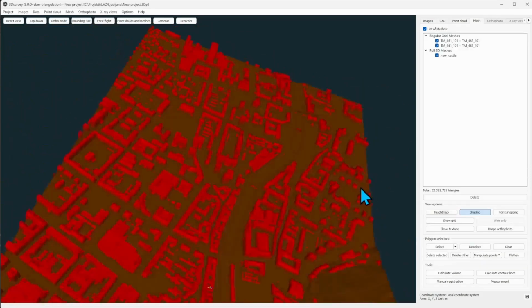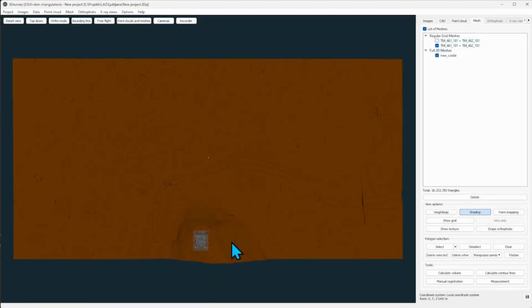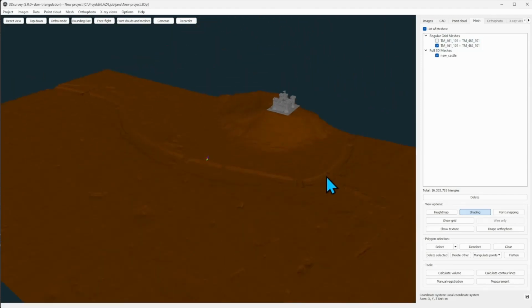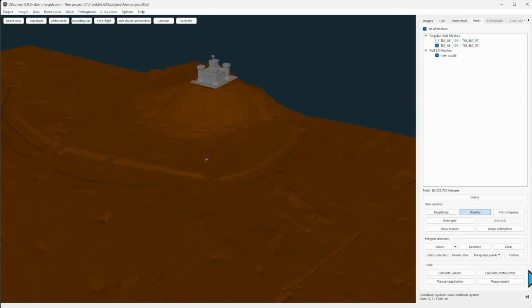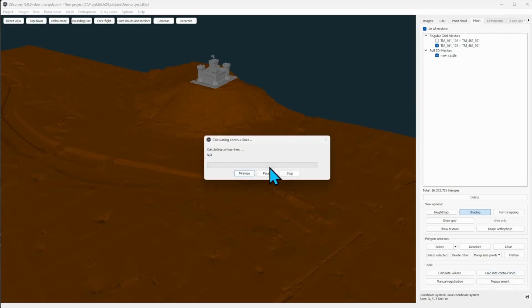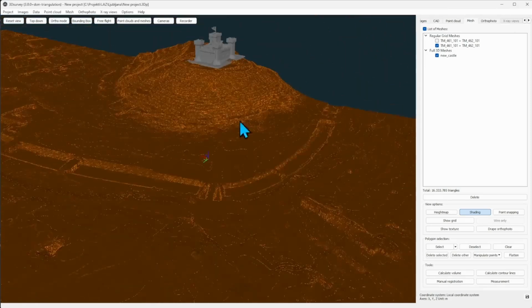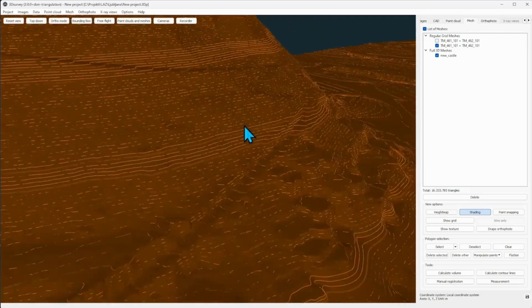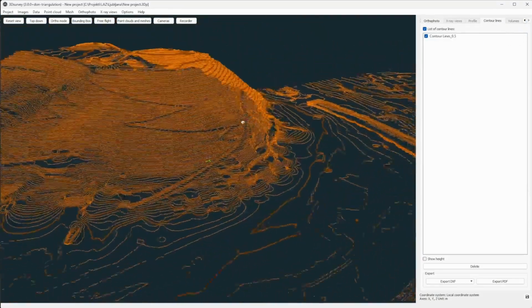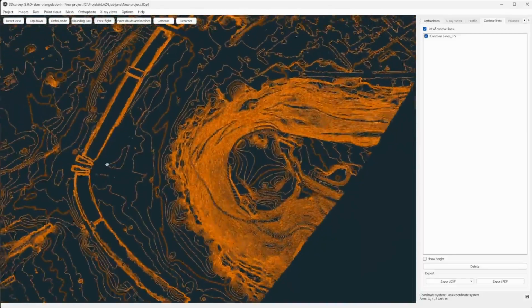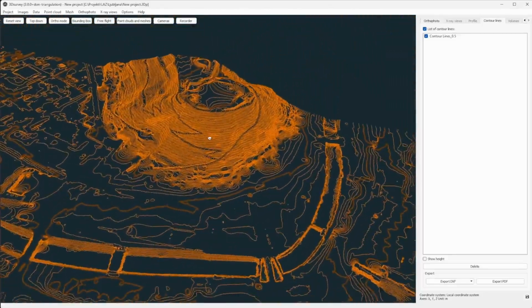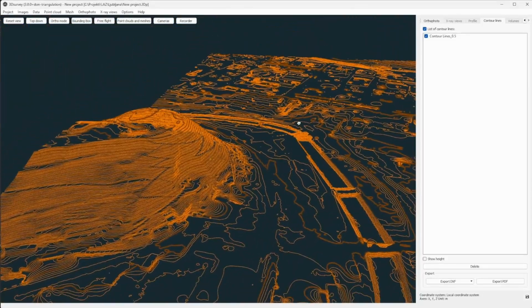Another thing I would like to show you on this case is you can do contour lines, which, if I may say, are in the process of improvement, but that's all I'll say. Soon they will be much more pretty. And it is generated really quickly on 0.5 meter equidistance, and that's the way we can visualize them in 3Dsurvey. All the pathways now are even better visible, see? And we can export them in DXF, in 3D or 2D.